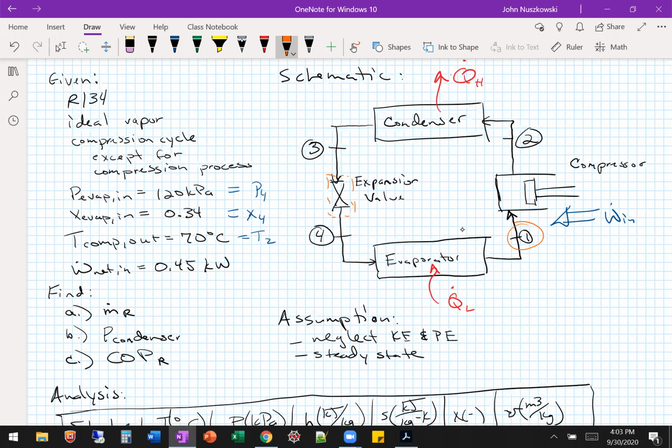So the only thing you're left with is mass flow rate carrying in enthalpy, mass flow rate carrying out enthalpy. The mass flow rate is the same, so you can divide it out, and you get that the enthalpy is the same from the inlet to the outlet. That doesn't change. From the conservation of energy, yep.